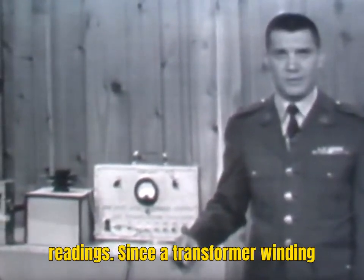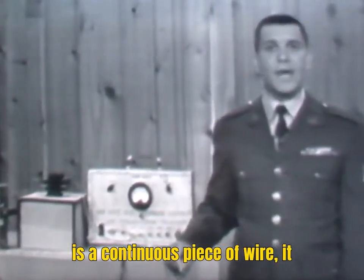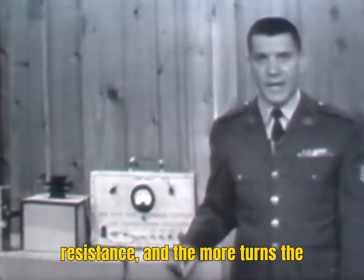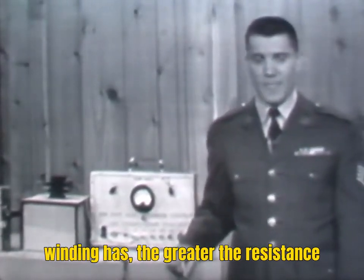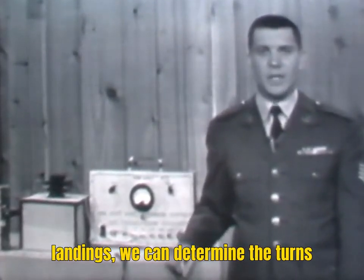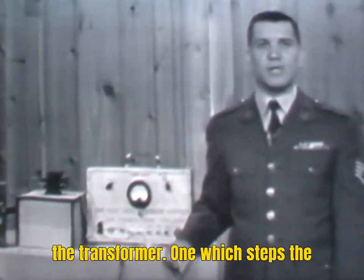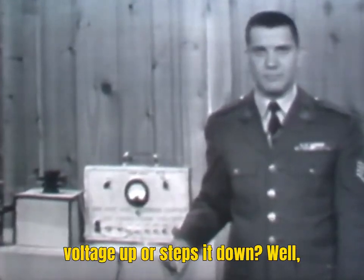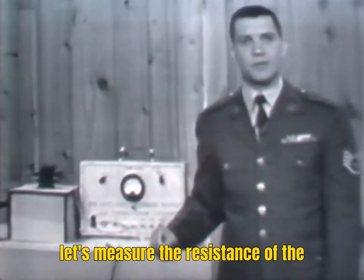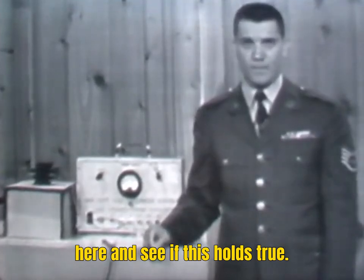Now, another way you can determine whether a transformer is a step-up or a step-down transformer is by means of resistance readings. Since a transformer winding is a continuous piece of wire, it should have a definite amount of resistance. And the more turns the winding has, the greater the resistance will be. Therefore, by comparing the resistance readings of the various windings, we can determine the turns ratio of the transformer, and thus whether the transformer is one which steps the voltage up or steps it down. Well, let's measure the resistance of the windings in our transformer and see if this holds true.